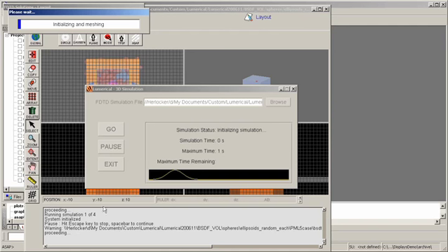We're simulating that geometry, and this geometry would be meshed out and a simulation done, and we would take the near field complex electromagnetic field, project it to the far field, and turn that into one bidirectional scattering distribution function. The randomization means that if we do this many times, the statistics will improve and we'll actually get a function that represents the result if we had an extensive surface, a macroscopic surface with these kinds of characteristics.